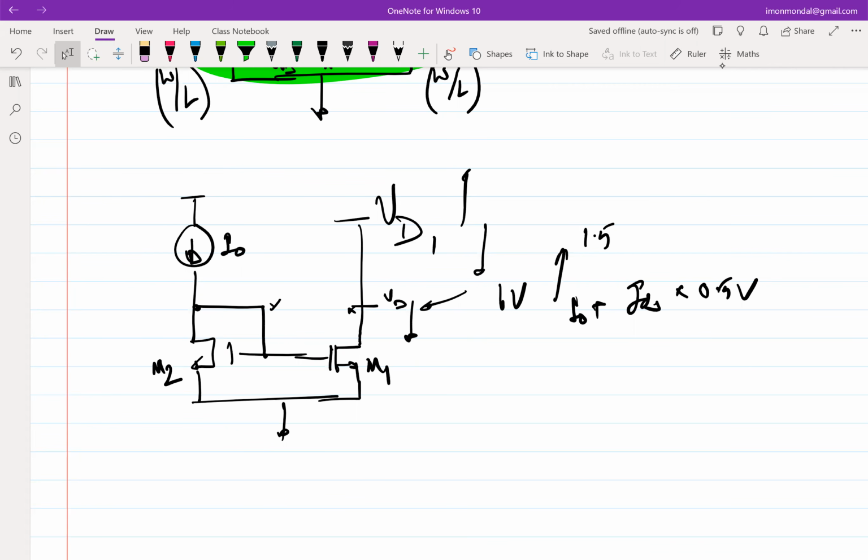Yeah, essentially that. So the trick to all these things is to figure out the condition under which you have exact current matching, even taking into account second order effects, and then assume that to be the quiescent and move up and down based on it. So that's, I mean, we have small signal analysis for neglecting small types of errors, then why not use it